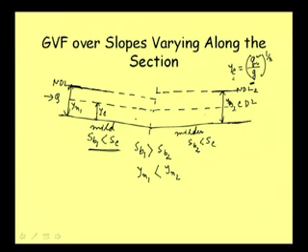For this downstream channel section, there is some disturbance at the upstream for this particular point, and as we know this is subcritical flow, so it is not influencing that, and we need not be worried about that part, as long as at downstream we have an infinite reach.